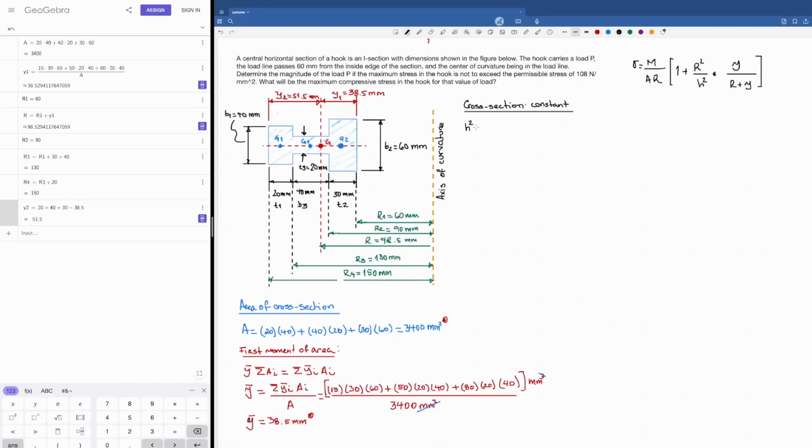Then it's going to be H2, and it is a long formula, but it makes sense. The way it is written is R3 divided by A. And then here, this is where it is important to remember each one of these nomenclature we're using to define the areas of the composite region that we're working with. So we have here B2 times the natural logarithm of R2 divided by R1, plus T3 times the natural logarithm of R3 divided by R2, then plus B1 that multiplies the natural logarithm of R4 divided by R3, and all of this minus R squared.